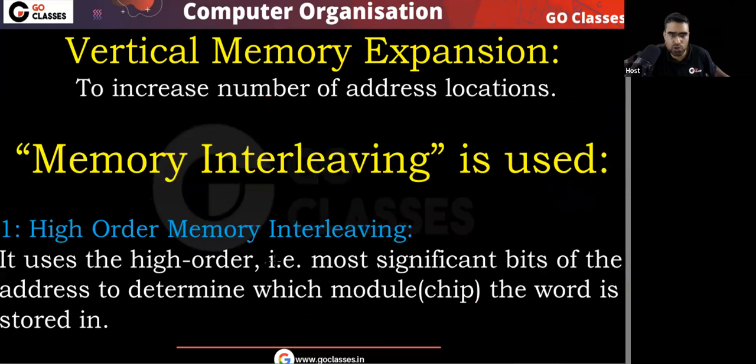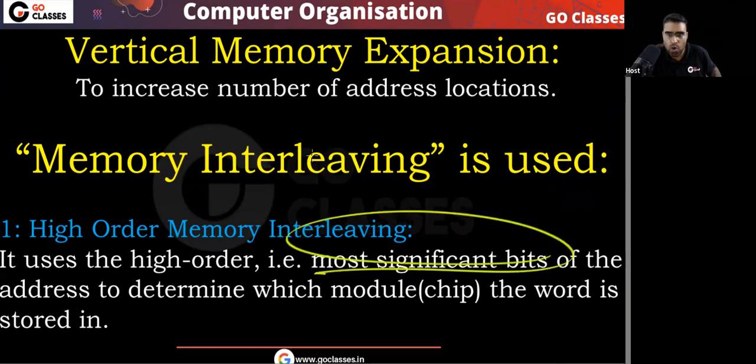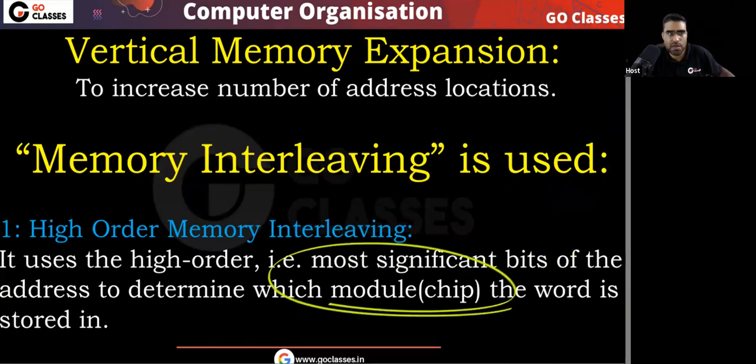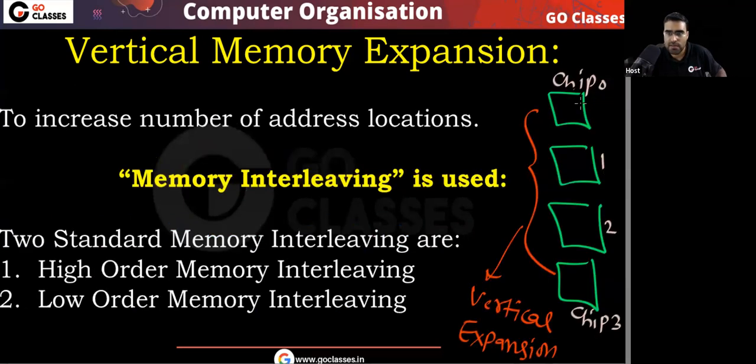So remember, the most significant bits of the address will be used to determine the chip in which the word is stored.